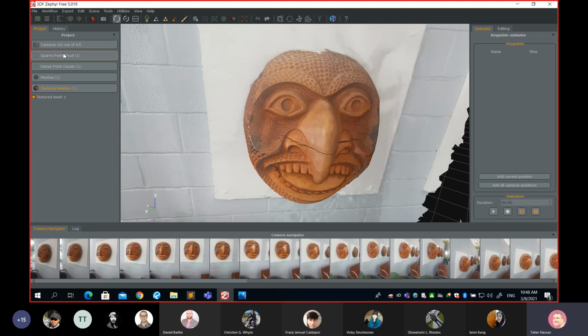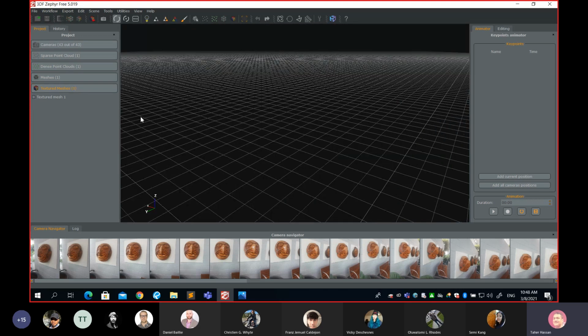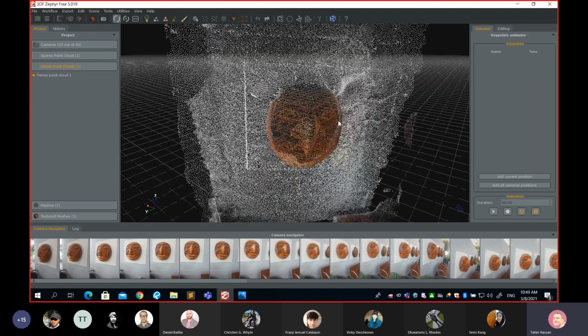You can see it goes from images to something called the sparse point cloud, which is turned off right now. Then you go to the dense point cloud, and it's turned off. Then we create a mesh, and then we create a 3D model. It's very interesting to see every product. So let's turn off this model, because I don't want to see the final results. This is your final result, which means I create a sparse model, I densify it, I connect the vertices and create a surface. You guys remember Civil 3D? Because this is somehow connected. In Civil 3D, we have points, and from points we created a surface. That's exactly what's happening here. If I show you the dense point cloud, watch this. Is that a surface or a point cloud?